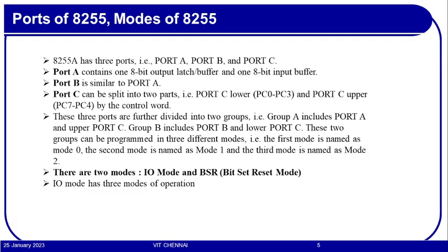The same thing we are seeing again. Port A is an 8-bit port, and it could be used as an input port or output port. When it is an output port, the data will be latched. Latch means it will be going through a latch, and from the latch it can be read. You know, flip-flops and latches. Similarly, when data is read, it will be buffered. It will be put in a buffer.